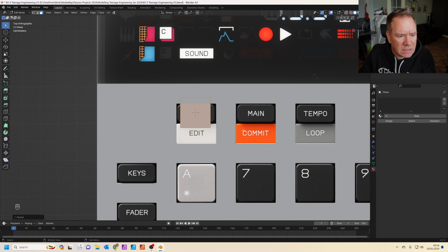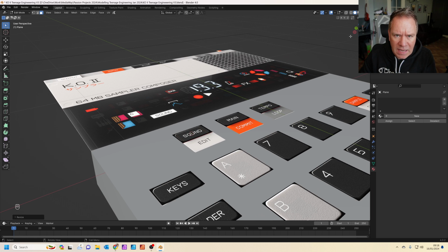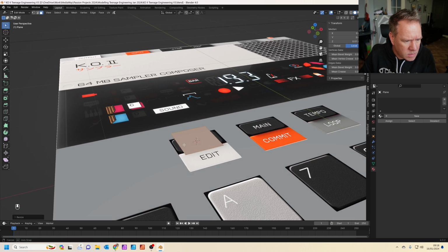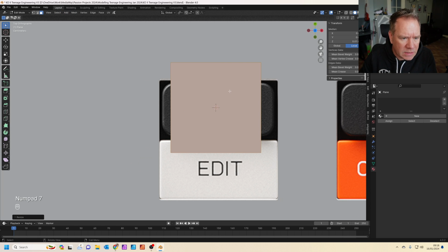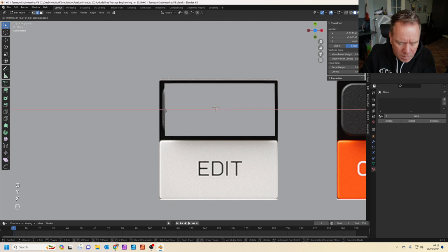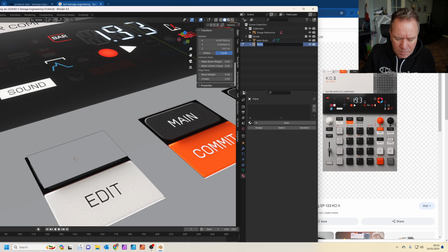Right, you'll notice it's disappearing, it's basically because all of these images and planes are all on the same Z reference. So if we just increase the Z plane, not too much, just by a fraction, that'll do. That should let us line it up better. So edge select, number 2, and we're aiming for the buttons at the minute, so grab these, line it up with the button just like that. We'll call this button.